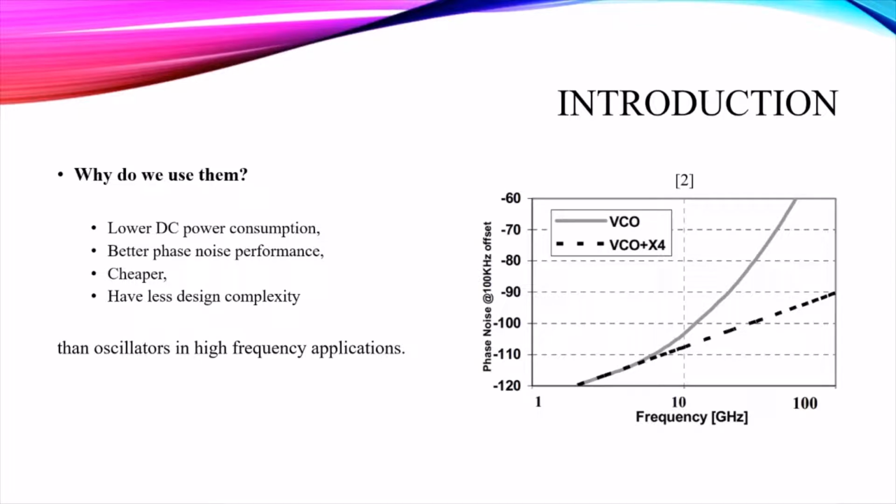As the frequency increases, not only does the design and implementation of a wideband low phase noise oscillator become difficult, but also the integration of PLLs at the fundamental frequencies requires wideband frequency dividers, which means prescaler circuits, which increases the system power and design complexity. This means oscillators can be challenging on power consumption and circuit design in high-frequency applications.